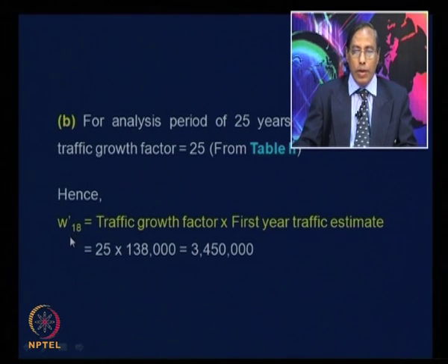Hence, W-18 will be equal to the traffic growth factor into the first year traffic estimate. So, the growth factor is 25 into 138,000, that means 3,450,000. So, this is W-18.